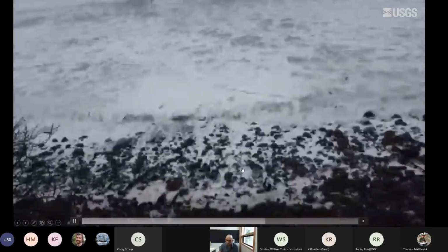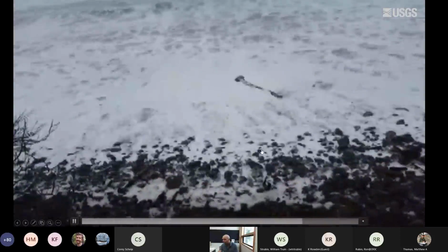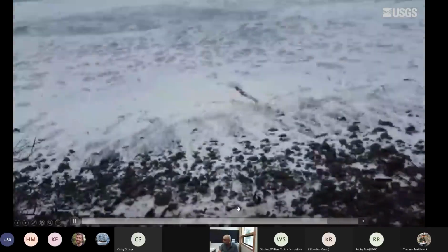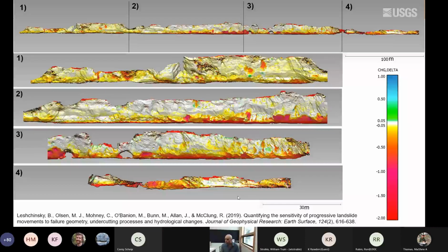And you can imagine that when it's high tide or there's a bigger storm surge, all of these projectiles are hitting the base of the bluff underneath this video. And that is a pretty abrasive force. So we can see significant retreat in a lot of these locations. Here's an example of retreat we've observed over 3 years at one of our sites, Beverly Beach, a lovely place with a great campground, by the way.